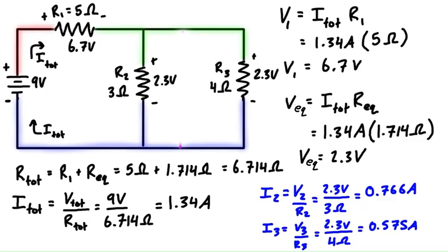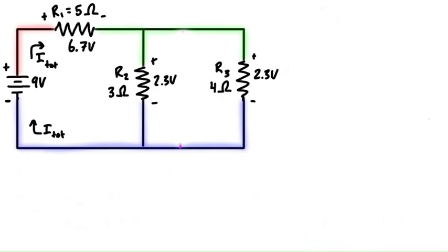But we can also use Kirchhoff's voltage law, which states that the algebraic sum of voltages around a loop is 0. So let's erase some of the work around the outside and take a look at this one loop at a time. Let's look at the right hand loop first. Let's just draw on a direction here. Let's go clockwise. Clockwise is a nice way to go. It doesn't have to be, but it's just nicer to look at.